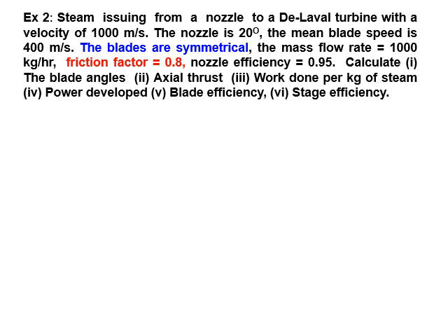Mass flow rate is 1000 kg per hour. So here m is equal to 1000 kg per hour. The mass is given in kg per hour, so now we need to convert that into kg per second. That means the mass flow rate is 1000 by 3600, since 1 hour is equal to 3600 seconds.